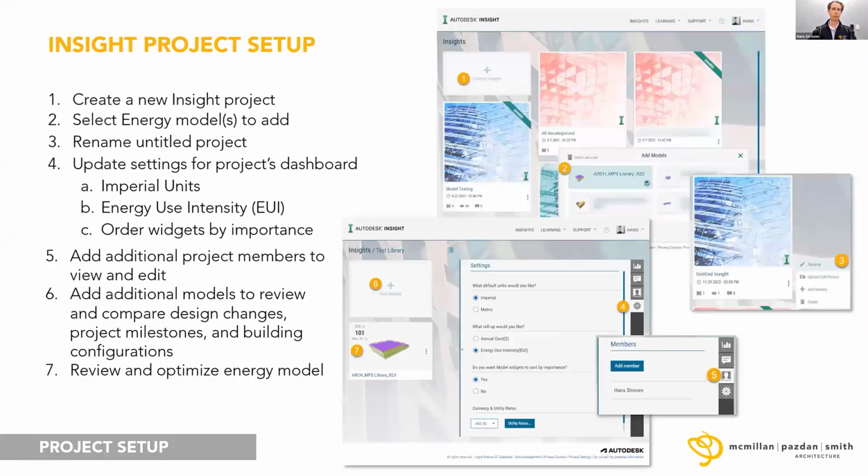So part of this too is once you push your model up to Insight for the very first time, you'll need to go ahead and set up your project. I'm not going to go through every step in here, but I do want to note to make sure to, depending upon which country you're doing this out of, set your units. By default, it's set to metric. So if you're operating out of the US, you'll want to set that to imperial units. And then also setting the energy use intensity, switching that over to your EUI.